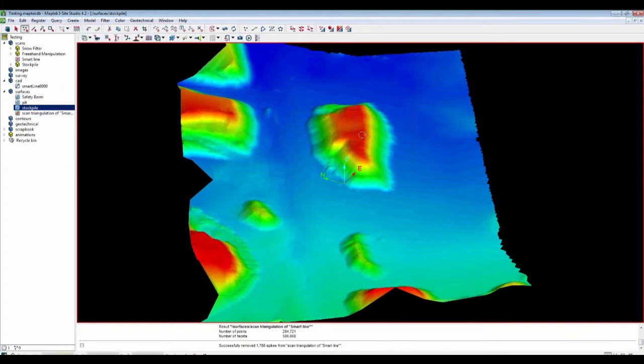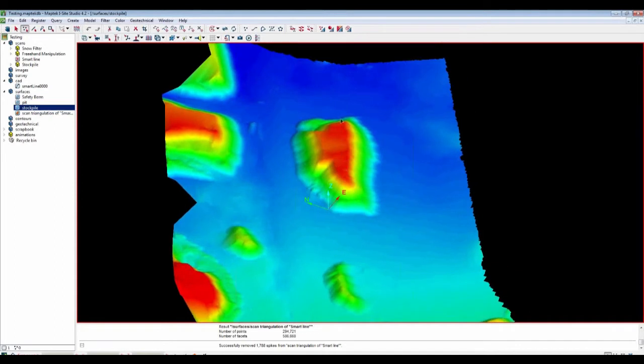So what I've done is I've gone to my Create Polygon tool, and I'm actually going to just really roughly digitize a polygon around the base of each one of these piles. If you were in a situation where you've got a familiar footprint or your stockpile on your site doesn't change that much, you could probably just do this once and then use that same polygon every week or month or however often you're reporting on that moving forward.